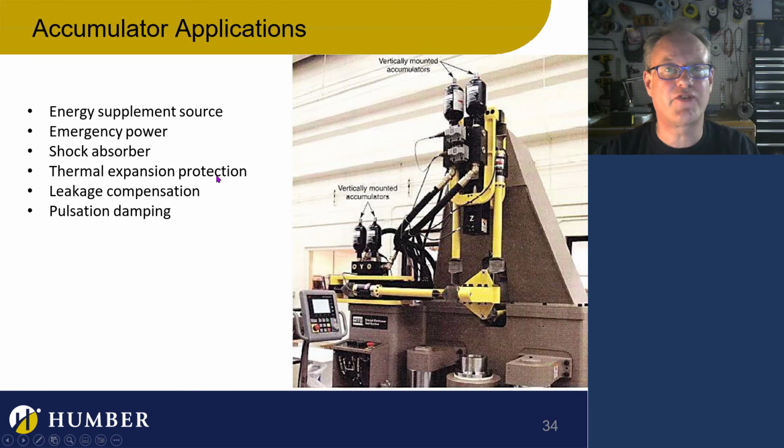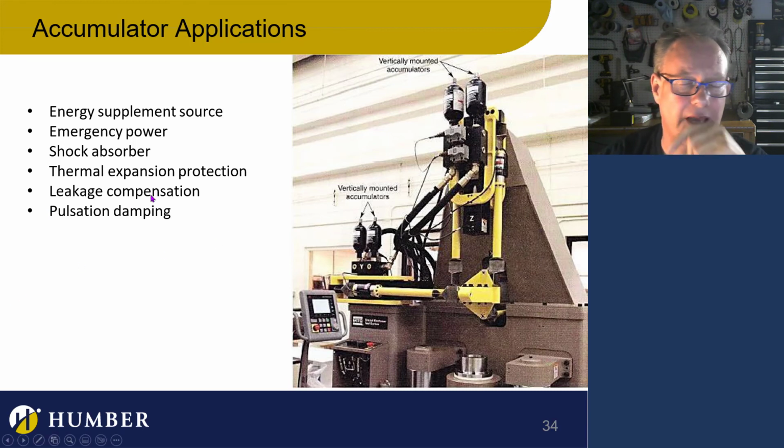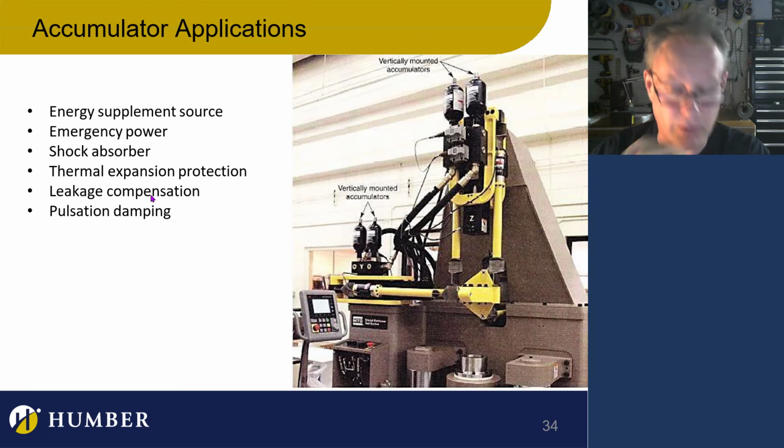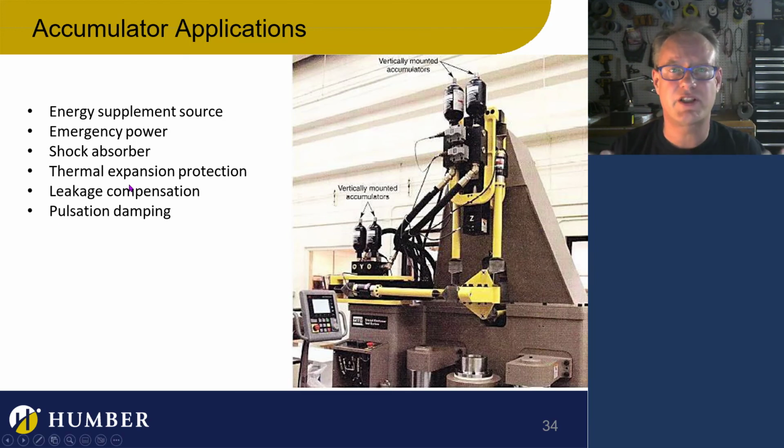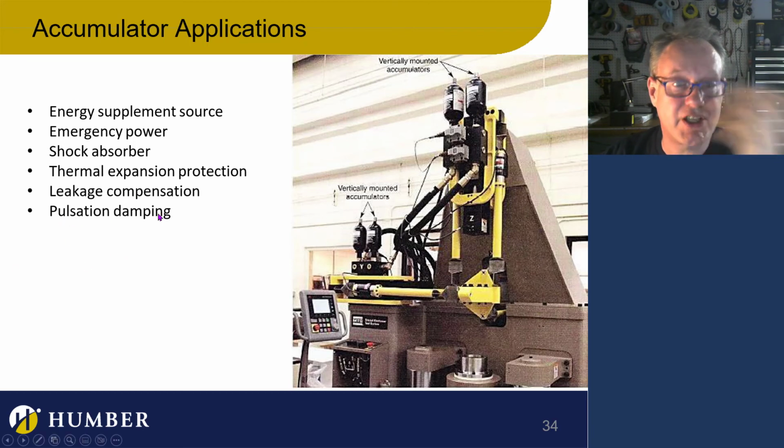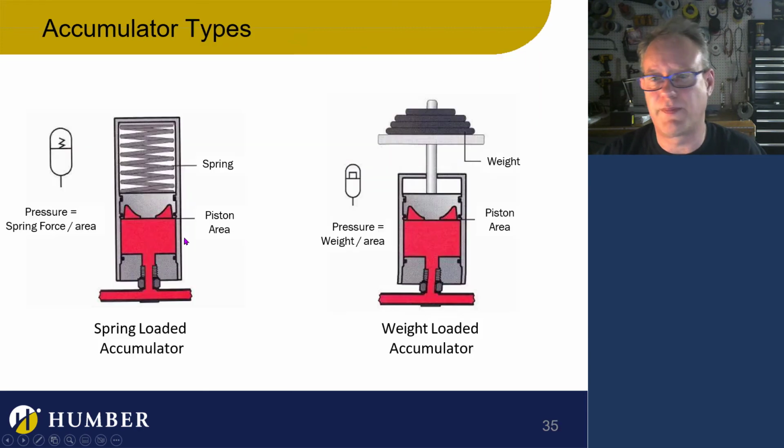Yeah, thermal expansion for sure. Like I said, when the fluid gets hot, it expands. Leakage compensation, oh yeah. Systems will leak, and you make sure that you deal with those leaks. And pulsation dampening. Yeah. So there you go. Accumulators are good for all of those things.